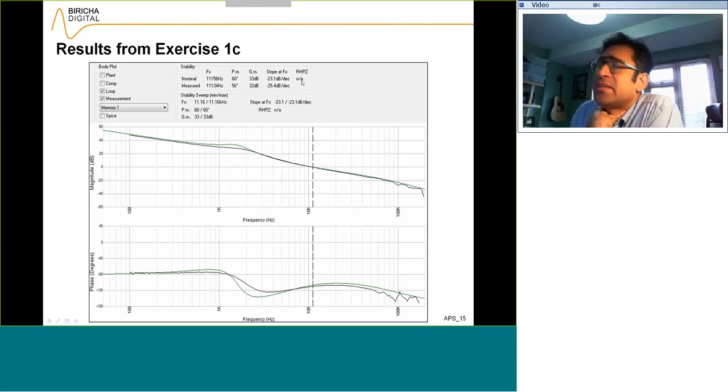Right-hand plane 0 is not available on a buck converter, so you don't have to worry about it. And then it gives you the measurement, and you can see the correlation between the measurement and the simulation, and you can see that it is matching almost perfectly in all of the values that you're interested in with regard to stability. The other thing that it gives you is the worst case values, the maximum and minimum.